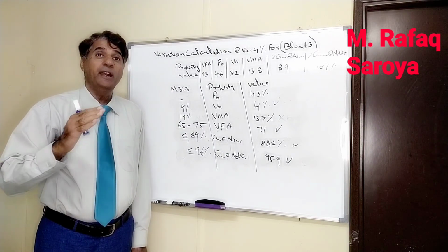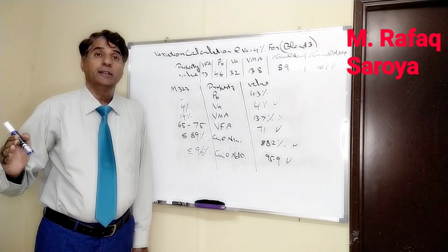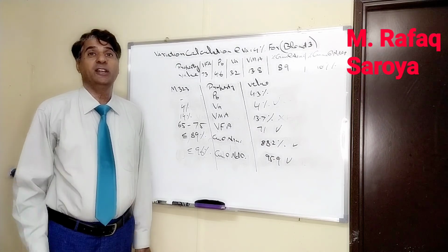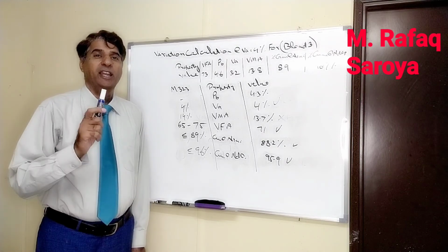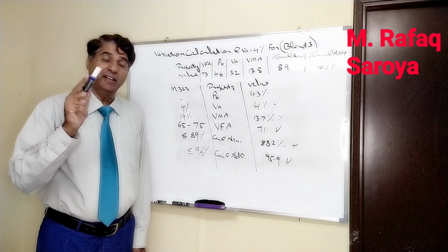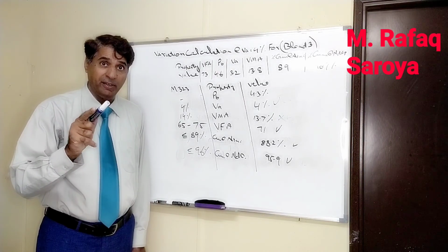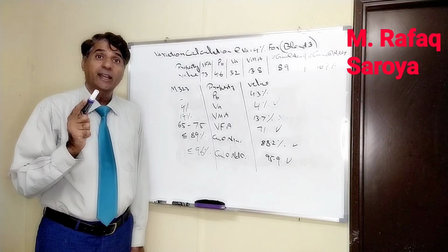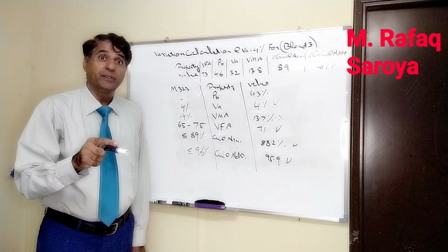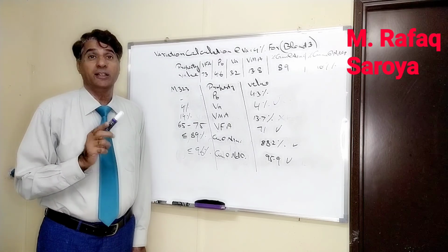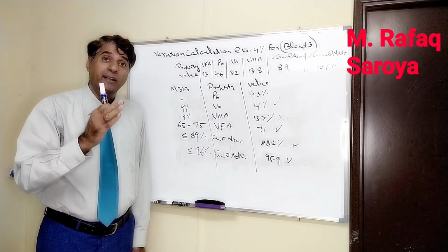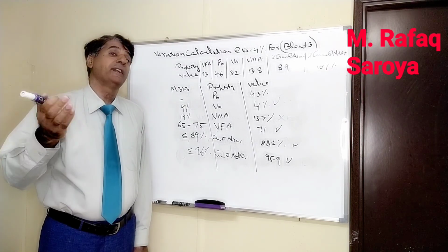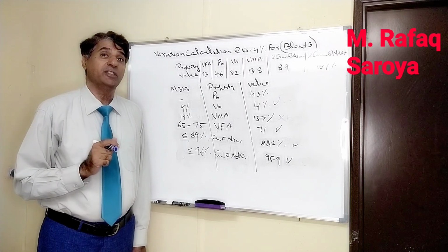So we will proceed further for the final evaluation of our mix design using blend 1 as our design aggregate structure. Please mark my word: blend 1 is our selected design aggregate structure, and the binder content coming through this discussion is our fundamental point for the further evaluation of our mix design.